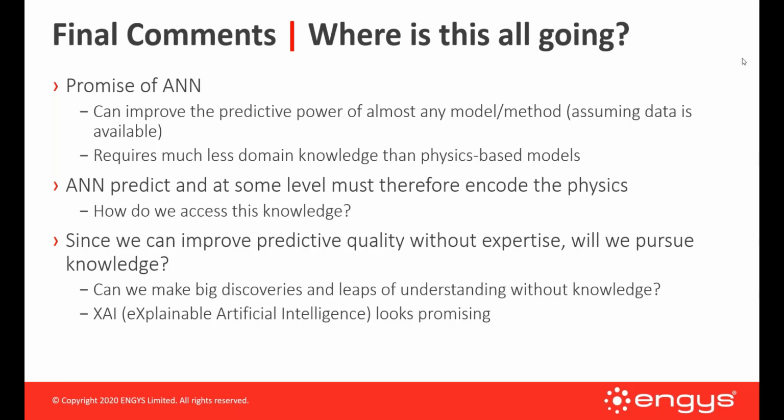If I'm running, I don't know, a 150 million cell DES or 200 million cell DES calculation on 1,000 cores, that'll take maybe 30 hours or so with our technology. That might be prohibitive. Let's say you have 24 hours per case and you want 1,000. It's 1,000 times 1,000 cores times a day, so it's a million CPU days. That could be quite expensive, but maybe that's warranted.